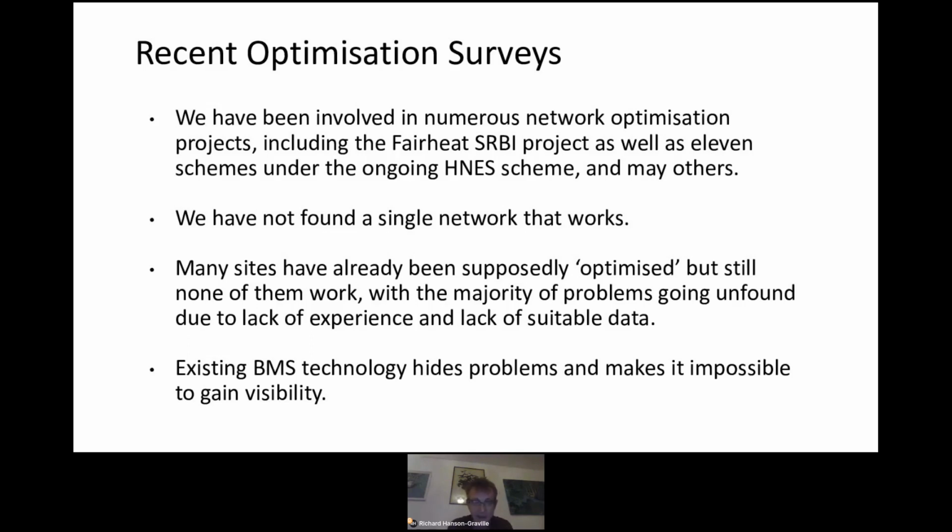The best spent money on any network is to put in visibility sensors, alarms. Then when things have failed, then you can fix them. So redundancy is pointless without alarms. If your primary device fails and it falls back to the second one and nobody knows it, well, then the second one will fail and it's down. So BMS is the key to this. It's really got to take the same step change, like BESA has been to HIUs. BMS has to take the same step change in quality for this to work, full stop.